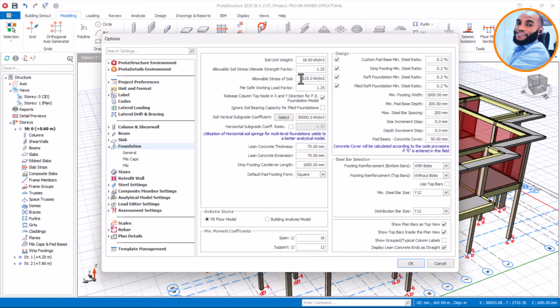When it's more than a 5-story building, a pad footing can no longer work. It will be very difficult because you'll be having a wider pad footing and also a bigger depth. And from the principle, the more you go in height, the more you need a deeper foundation to transfer the load of the structure to a suitable soil strata.